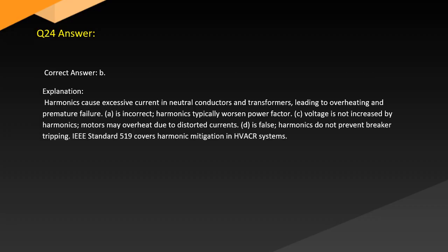Answer. Correct answer: B. Explanation: Harmonics cause excessive current in neutral conductors and transformers, leading to overheating and premature failure. A is incorrect. Harmonics typically worsen power factor.